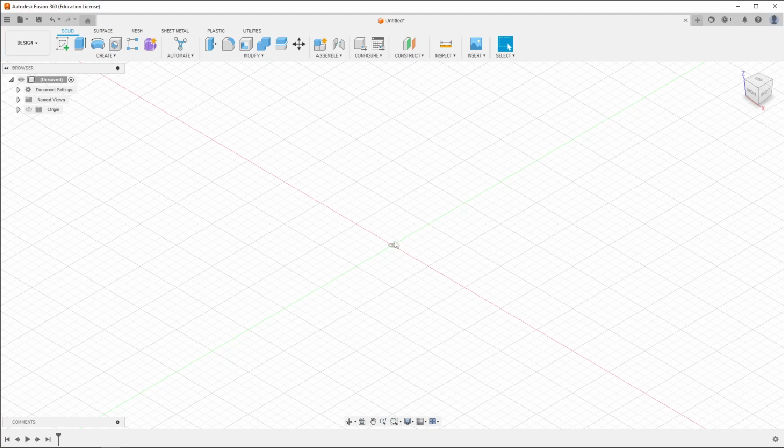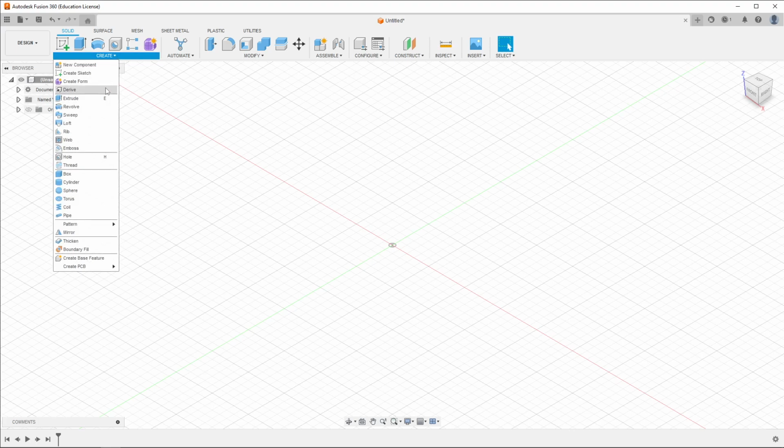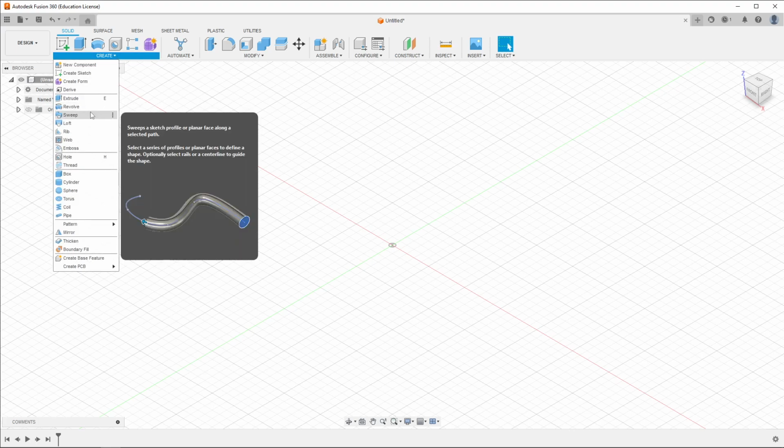In this video we're going to focus on talking about the sweep tool, which is another powerful tool in creating more advanced shapes. Essentially, we can take some closed shape or profile from a sketch and move it along a path in a different direction, and the end result is a 3D object. For example, making handlebars or potentially table legs or chair arms and things like that that have curves or different bends to them. We can do them all at once as a single object, and that's a very powerful tool to have.